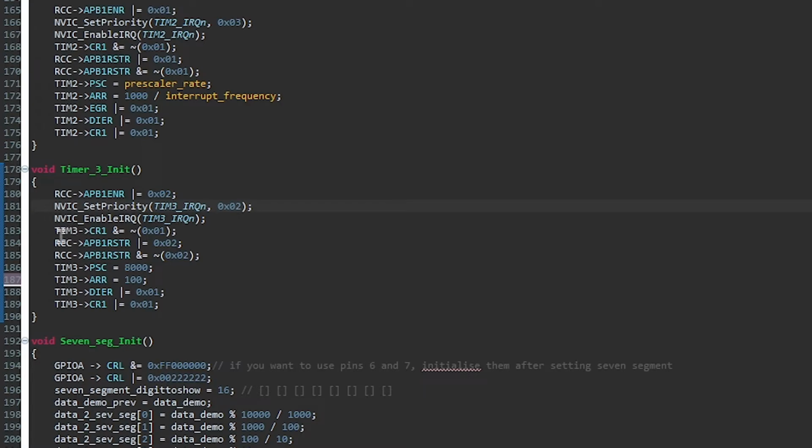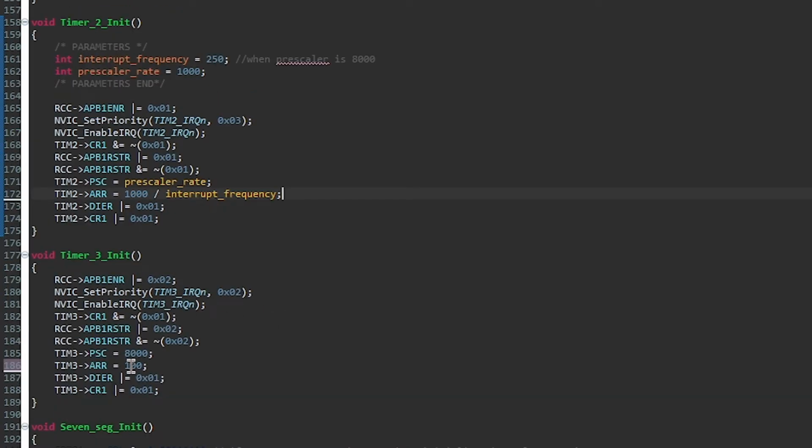Now, turning off the timer and resetting it is important when we actually want to reconfigure our timer. Once we initialize it for the first time, these moves are, I think, not necessary here. So you are free to experiment here. I will leave them as they are, but I believe it's not necessary. Alright, I think I've figured the problem out here, and our timer should respond much faster. We shouldn't see such delays when I press the button.